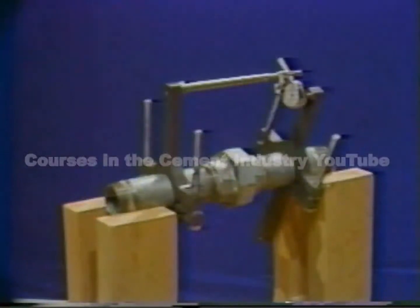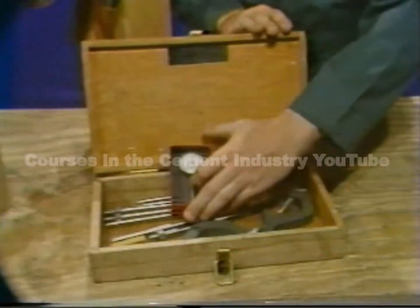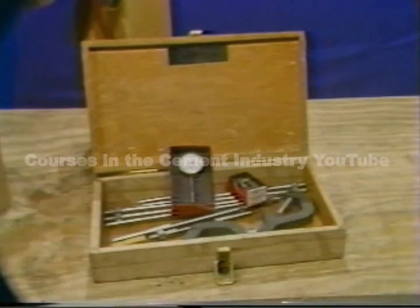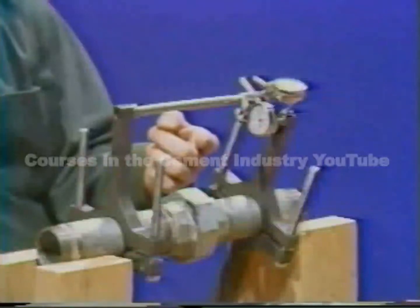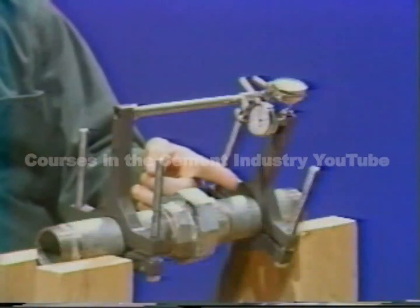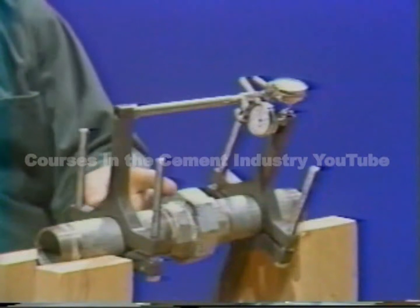There are several ways to mount the dials. The one I like to use involves an alignment kit. Let's look at a mock-up so you can see how it works. Think of these two pipes as the shafts of the machines we're aligning. The union between them represents a coupling.